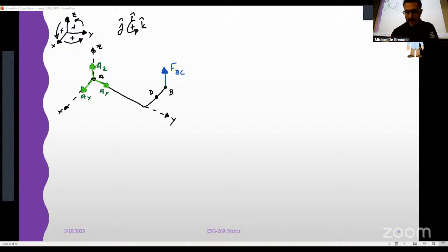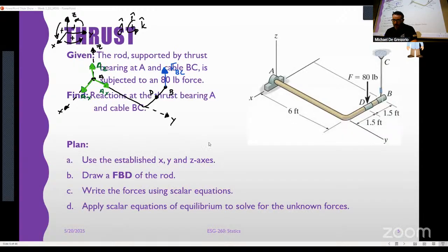And so if it allows spinning, it looks like, if you go back to the original drawing, which we will do just to highlight this, you can clearly see that the shaft goes through here. So this should be allowed to spin around the y-axis, but we don't want this thrust bearing to bend, right? We don't want it to bend around the z, and we don't want it to bend around x, right? And so we're going to resist those motions, and typically down here, right? And that would keep it in place.